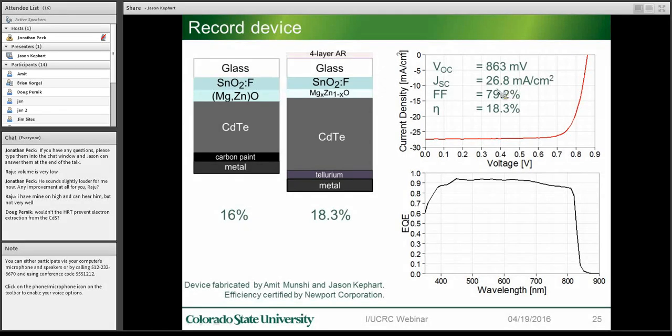And before we went to this high temperature cadmium telluride, we couldn't make a fill factor much above 76, so this is really a large improvement. You can see the quantum efficiency is over 90% over a wide wavelength range, and this decrease is primarily due to the anti-reflection coating. I'd like to again stress that this device uses only high throughput manufacturable techniques, and it's not much more complicated than the 12% devices we used to make.